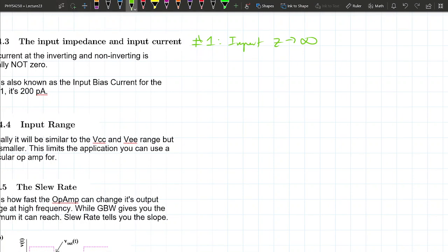You guys remember that from first day? How does a voltmeter work? There's a little needle, right? Well, used to be a little needle. What's at the end of this needle? A little coil, right? That allows current to run through it. And around this coil, there's a magnet, right? North and the south, right? When you run current through it, it deflects the coil because of the magnetic force, right? So in order to measure voltage, you need current,